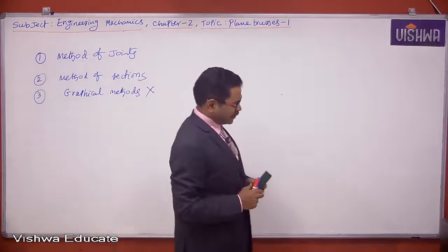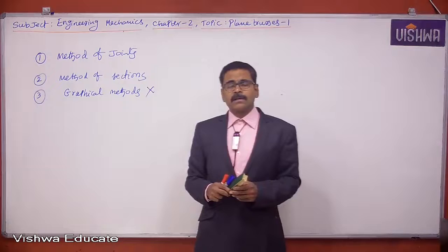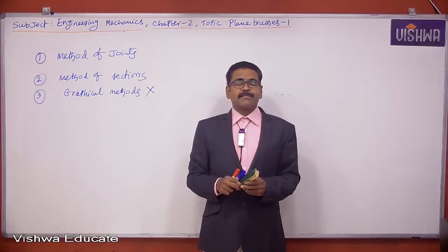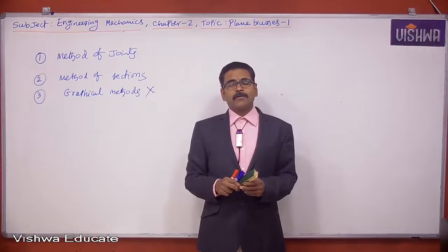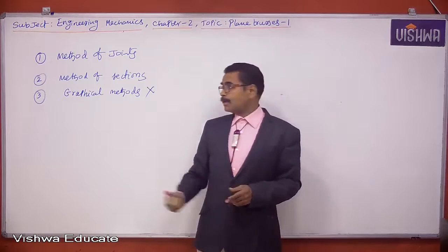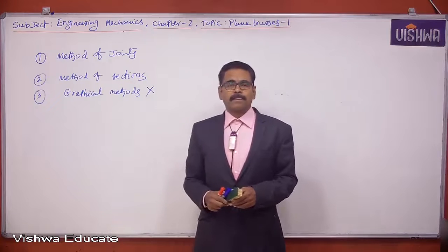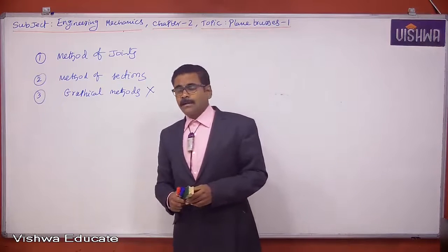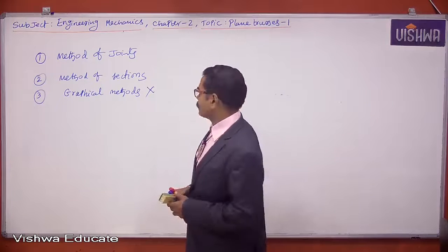If a truss is given, try to examine whether it is forming a collapsible truss or a non-collapsible truss. If it is a collapsible truss, definitely the load carried by any member of the collapsible truss is 0. I already explained this some 5 minutes back. I took one example of a collapsible truss or under rigid truss and explained there. This is the first shortcut.